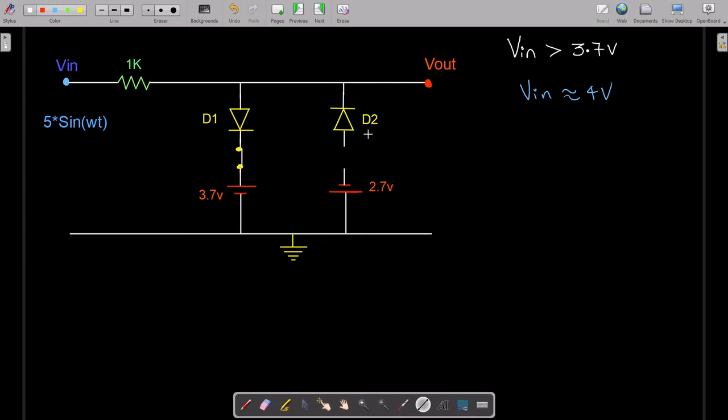So due to this, if you could see very clearly what is going to happen, a current is going to flow in this particular direction. See, from here to here to here, okay. So this is how your current is going to flow. Let me erase this particular thing and we'll draw only this particular part below. It would be something like this. I won't draw this particular diode. Yeah, so this is your plus minus 3.7 volts, okay. I'm neglecting this particular diode, and this is your output, V out,